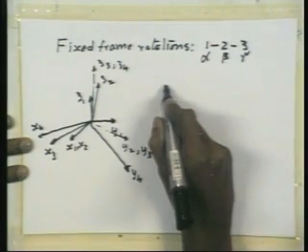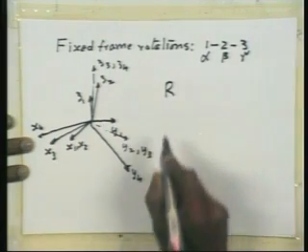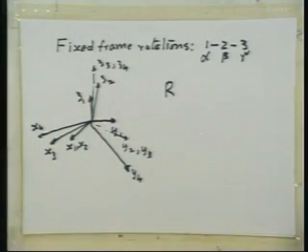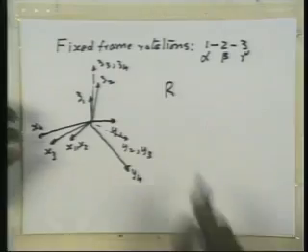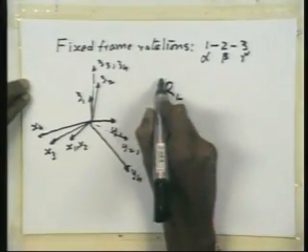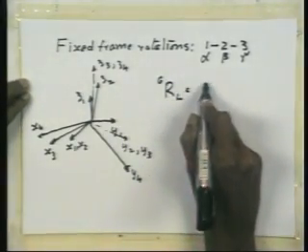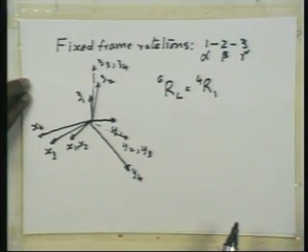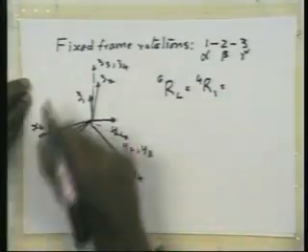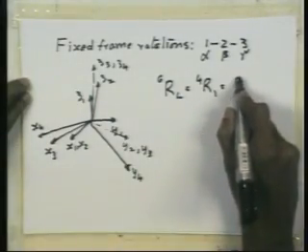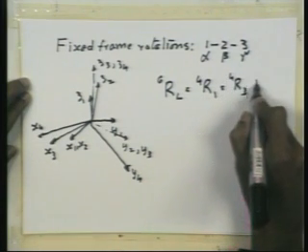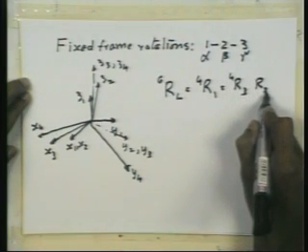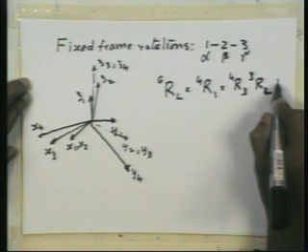And now the rotation matrix which corresponds to the local to global. Which is the local and which is the global now? The local is x1, y1, z1, and the global now is x4, y4, z4. The rotation matrix that we are talking about from local to global is what? Is from 1 to 4. Right? So based on the notation we have given, this is 3 to 4, 2 to 3, and 1 to 2.